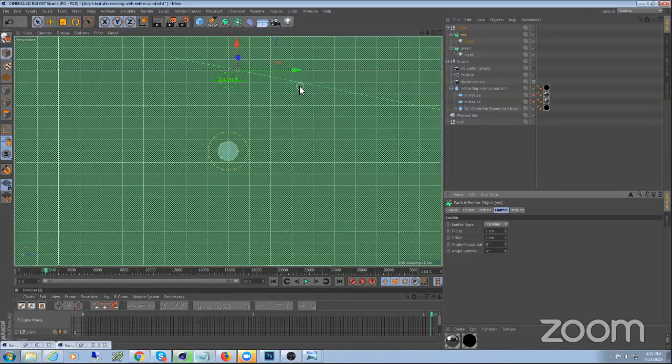And what if you make it 0.1 or 0.01 centimeters? Maybe it doesn't matter. You can make it a micron in size, and it would still do the same thing. It would still emit in a sequence, and there would be an offset between each particle. It's a problem that you can overcome just by offsetting your emitter in this setup, so that the first particle it drops is dropped when it's at exactly X and in this case Z0, and then it drops down on the Y axis. Oh, I see. And that's what I did.